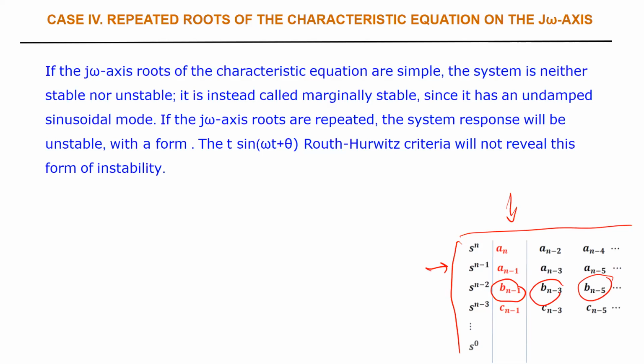So from here, I can write the auxiliary equation, and then I differentiate the elements of the auxiliary equation, and then I proceed. If you have an auxiliary equation, most likely you will have either 2 poles in here or one here, one here. Most of the time you will have the pole on the j omega axis.